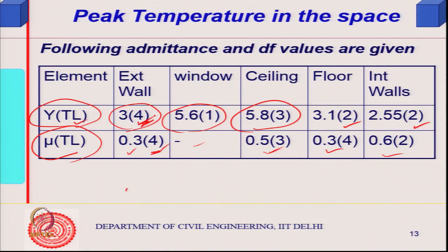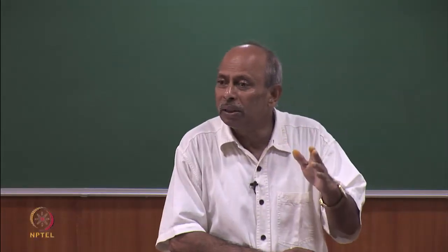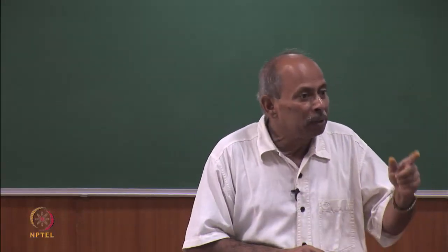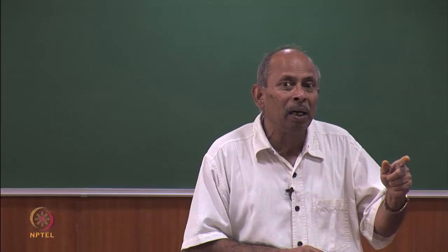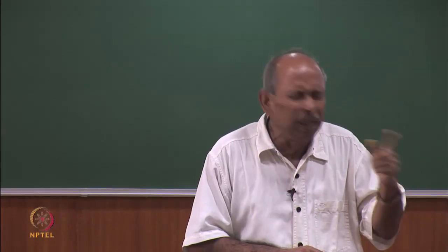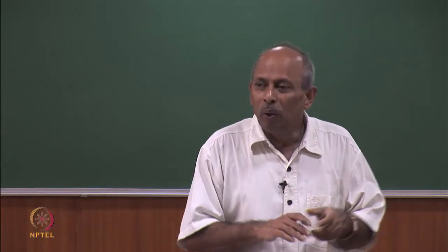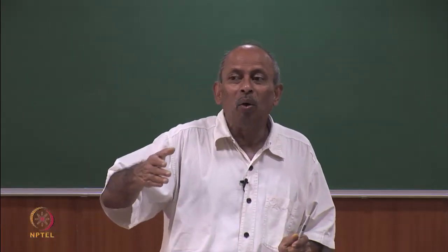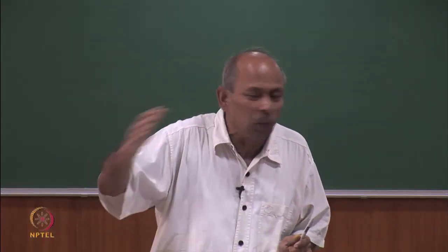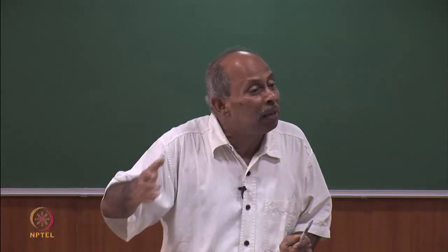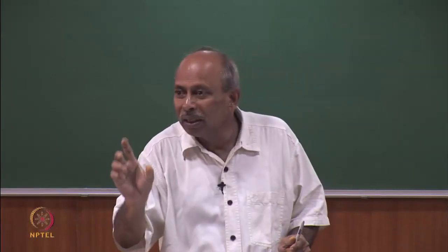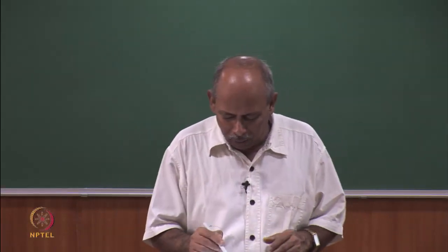So, for the temperature at 18 minus 4, that is 14, minus another 4, because the radiation at 10 am will actually be entering into the room at 2 pm, 10 plus 4, but that will cause a temperature rise at 6 pm. So, 8 hours I must take into account.